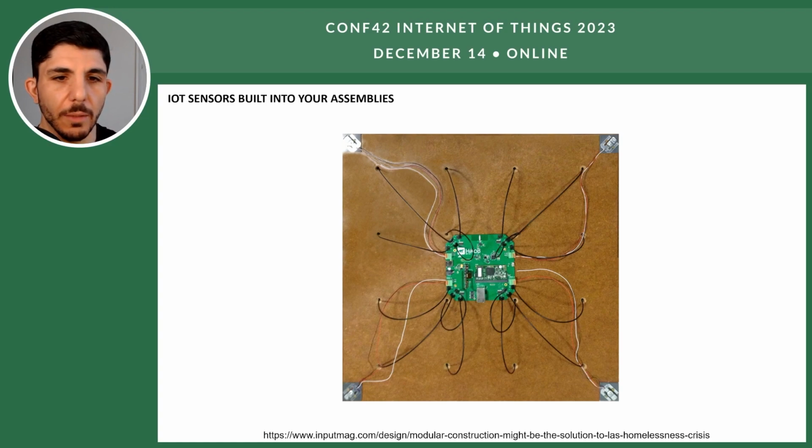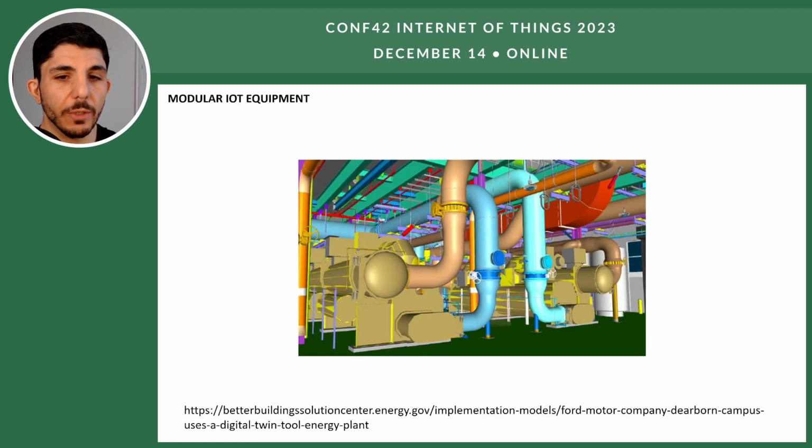I mentioned earlier about the plumbing in the school. There's a serious issue with a lot of buildings where they leak and it causes a lot of damage in the hundreds of thousands of dollars. And they're starting to use hygrometers that are small and compact and retrofitting buildings with them. So if there is a water alert, a humidity alert, it can go to a central database. And it's as simple as something like this, where you can quickly wire it up or use wireless methods of reporting it, so that with a modest investment, you can avoid serious cost overruns. So it doesn't have to be this huge, challenging project, but it can be.